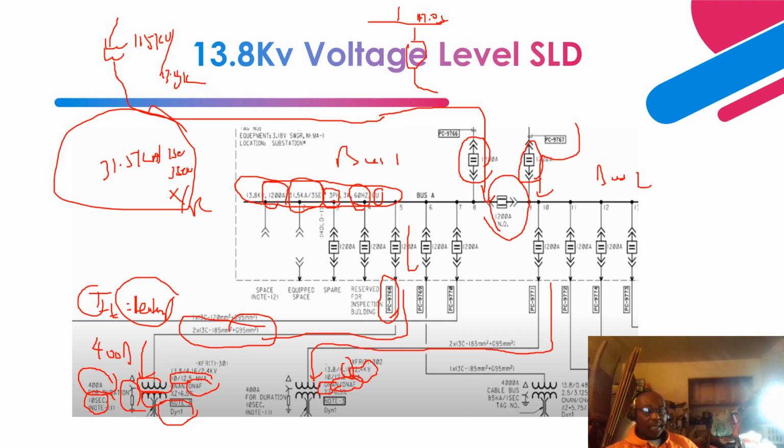Okay, and the low voltage side is Y resistance grounded, and this is very important, especially for industrial facilities, right? Where you want continuous operation, to limit the damage to the equipment. So the amount of fault current that will allow the ground fault currents to identify the fault and trip the equipment is 400 amps, and the maximum duration is 10 seconds, right? This is how much the resistor can withstand without any failure, right?